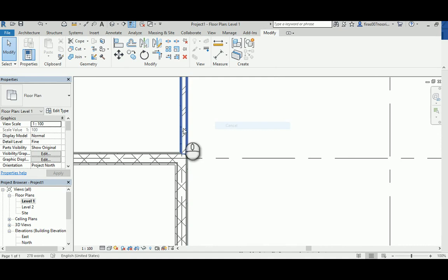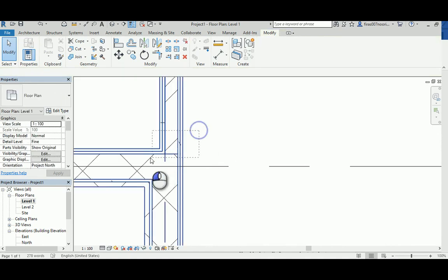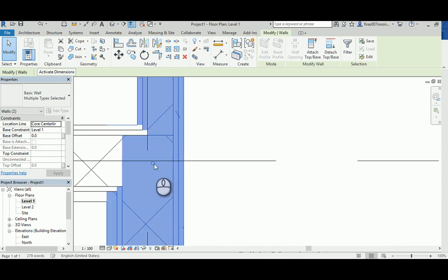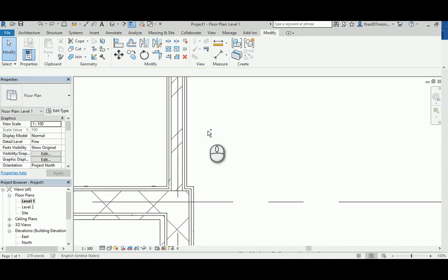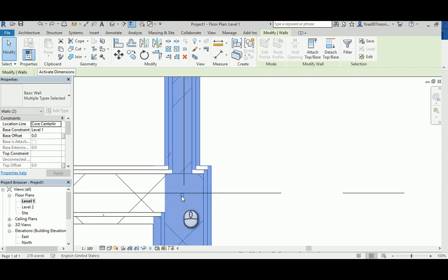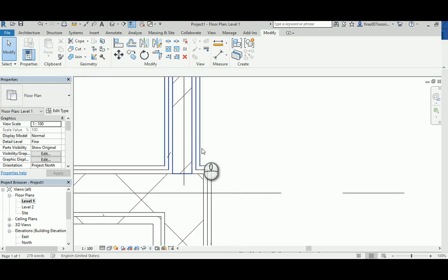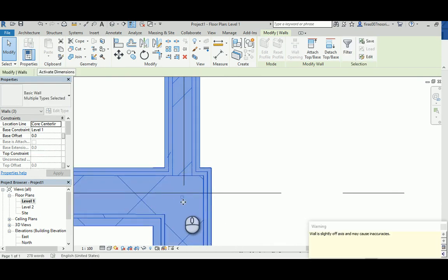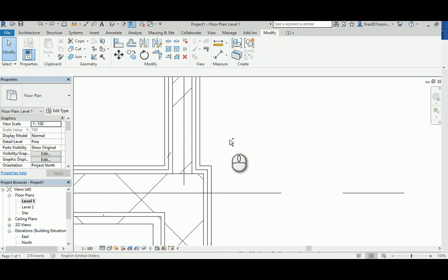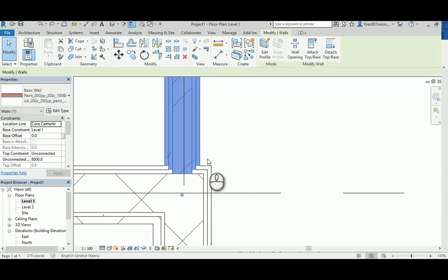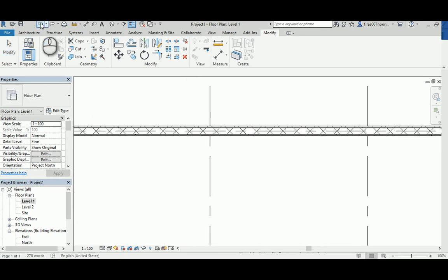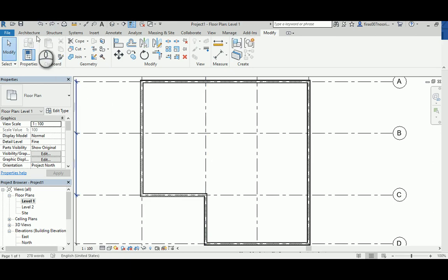So be aware of the type of joining that you have when you select a group of walls, or at least when you select 2 walls. See, now they are actually joined, not joined, but if you select this guy, and you join them, I think it doesn't join yet. Yeah, anyway, it doesn't join by any. So I believe the best thing to be done is to undo actually a couple of times. Yeah, redo. The best way to do it is